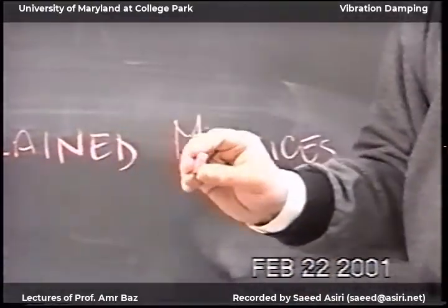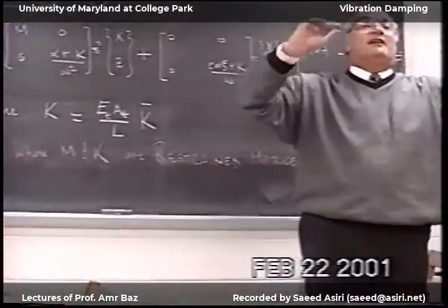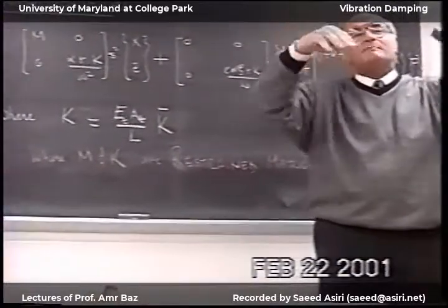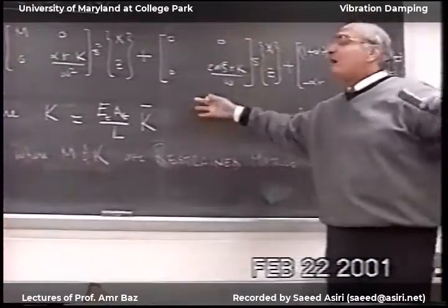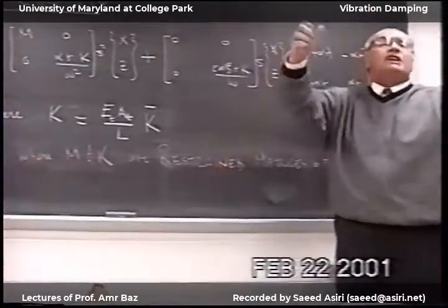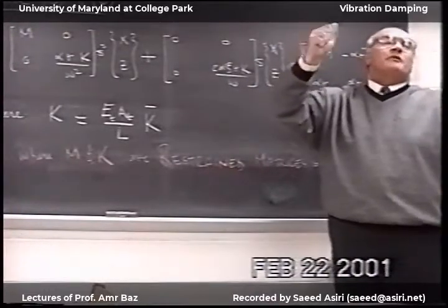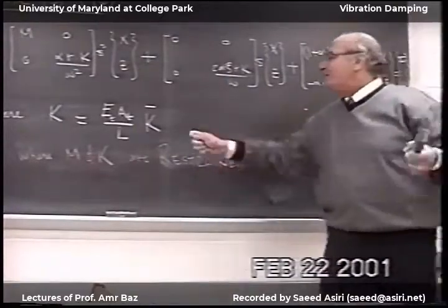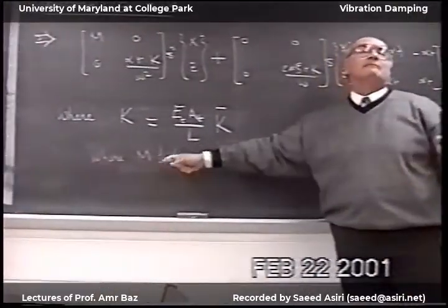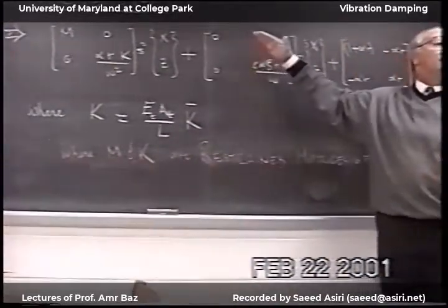Or we can say, if my element is, for example, a flying platform, like we said a rocket, or any space station, it is unrestrained. To make this work, I have to take the 0 frequency degrees of freedom, or the rigid body modes, out of the stiffness matrix and the mass matrix of the system. If you don't do this, nothing will work. Okay?